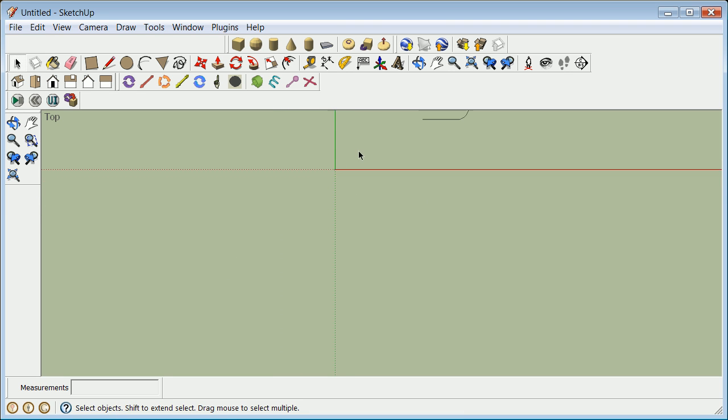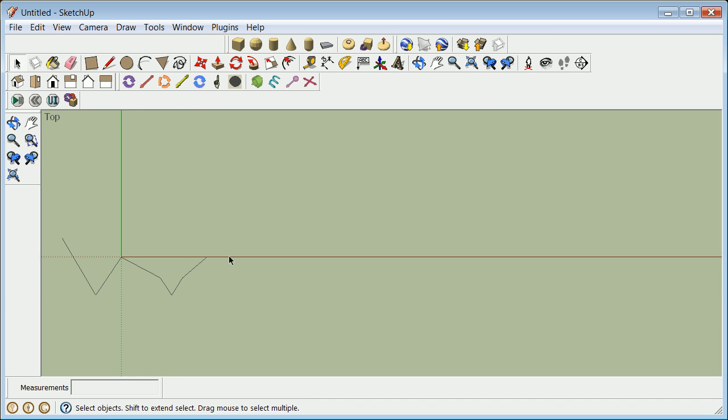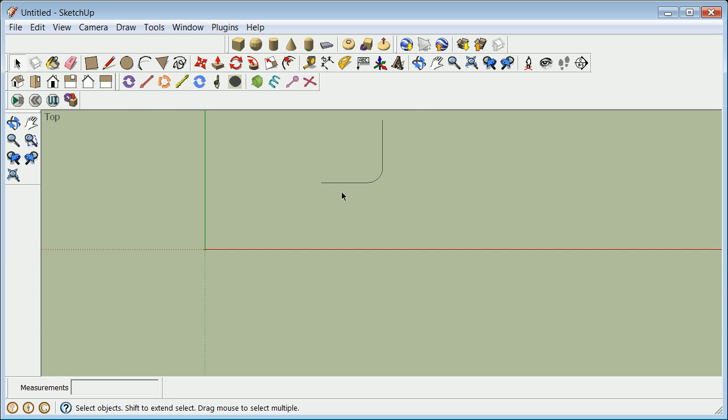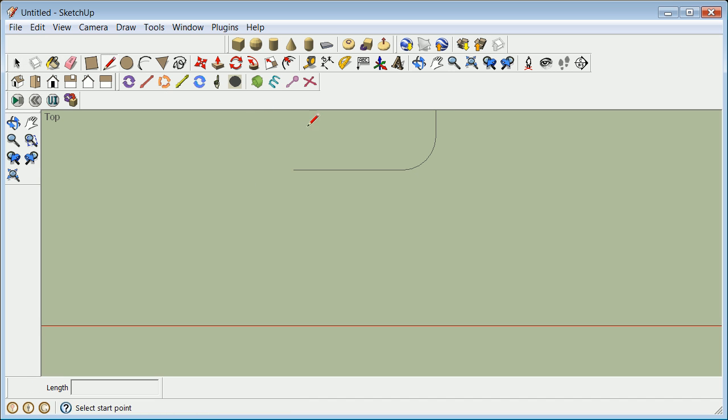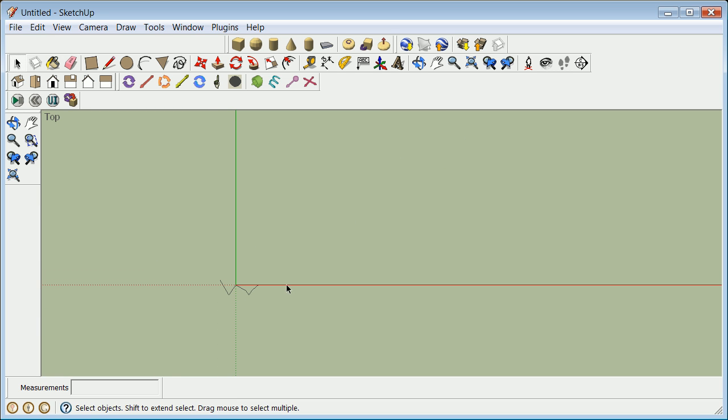Now, what is the mathematics of getting this turned to any direction here? It is a question of rotating about the x-axis and then rotating about the z-axis. So what I'm going to do is draft from here. I can't really grab the center, can I? That looks like it's the center, so I'm going to draft some arbitrary direction there. And of course you know that that direction is 90 degrees from the tangent direction. So what I want to do is rotate this shape first about the x-axis, then about that axis, which we're going to bring over here, and then we're going to move it.